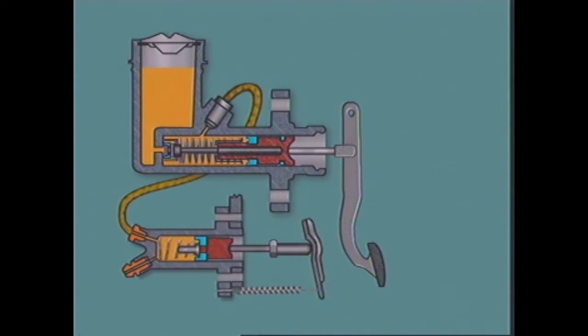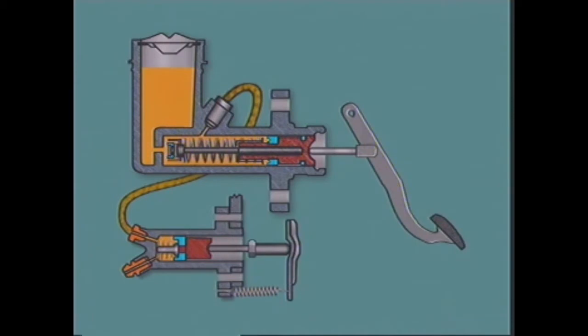When the pedal is released, displaced fluid returns to the master cylinder, and the center valve returns to being slightly clear of the inlet port.